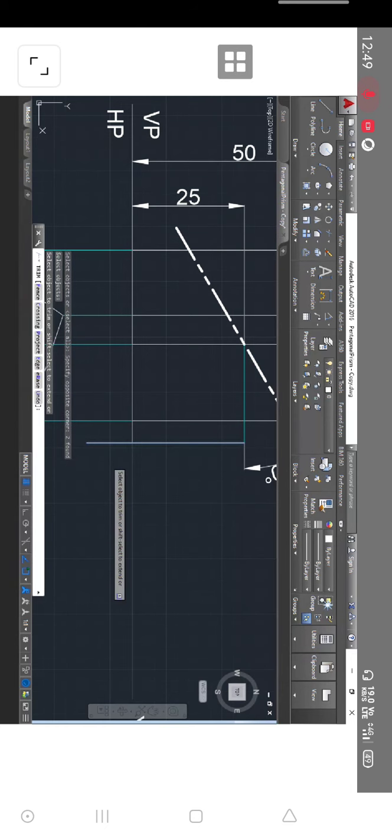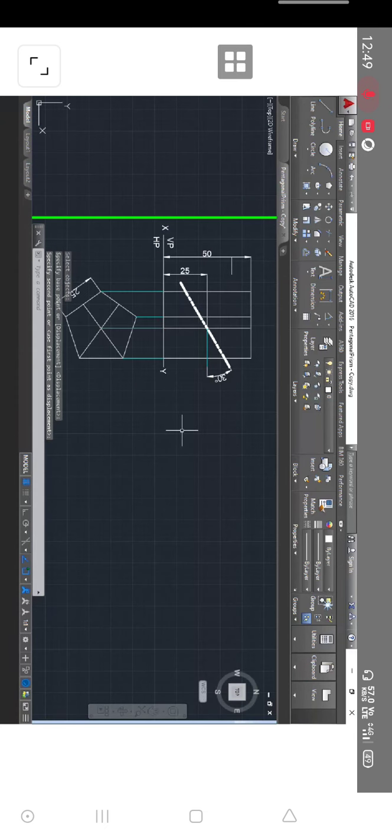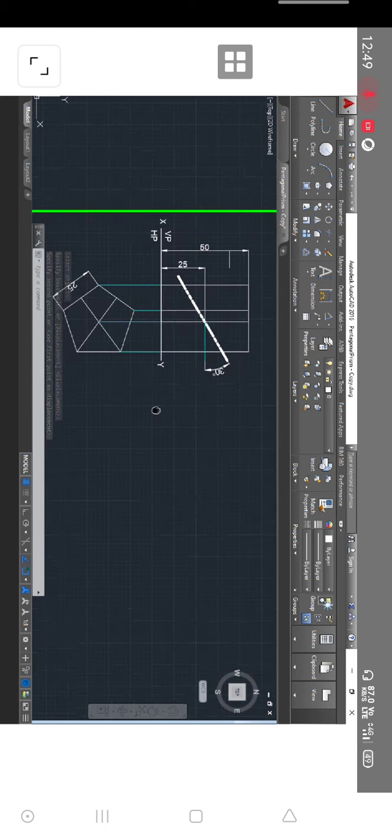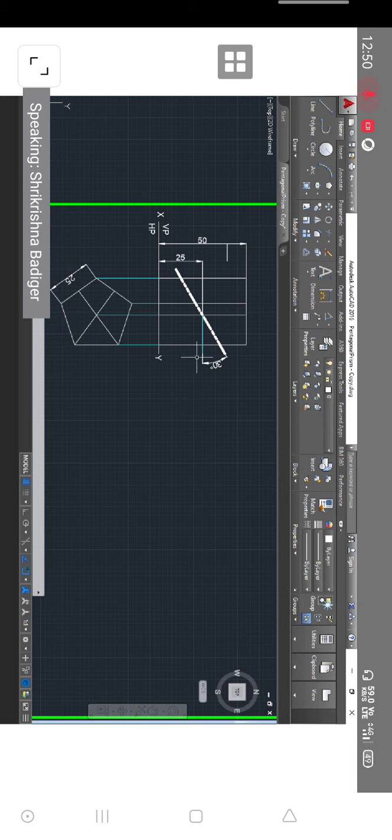I'm going to move this X Y here, point to Y here. Now, always for a prism, the preferred way of development is this: the true heights of these edges and faces are right here in the front view. So you use the front view itself as a development.